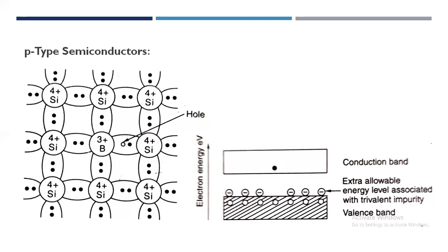The act of stealing an electron from the silicon by an impurity atom produces a hole, similar to the holes arising from the breaking of covalent bonds. This hole moves about randomly due to thermal effects, and when an electric field is applied, it tends to drift towards the negative terminal, contributing to the flow of current.